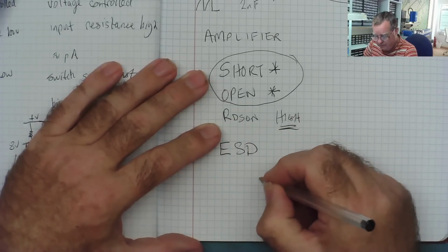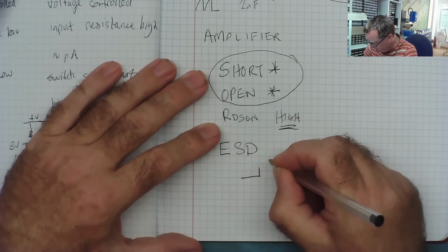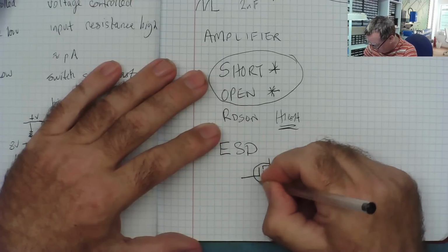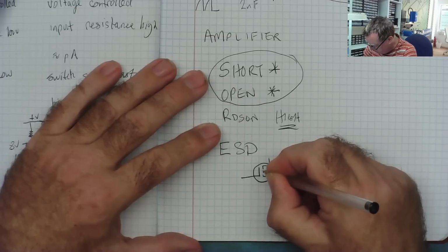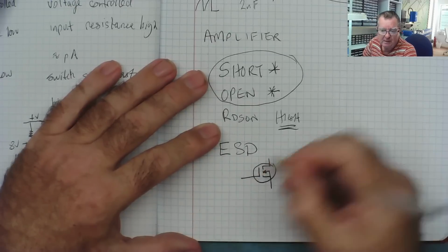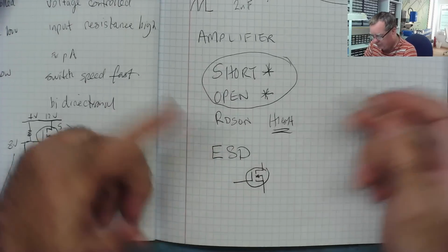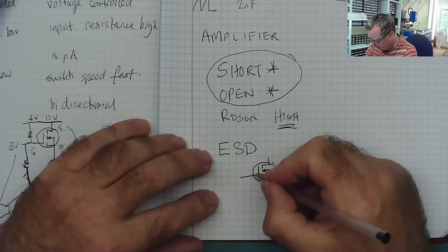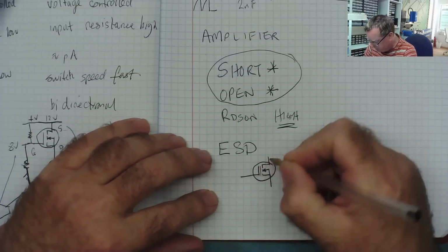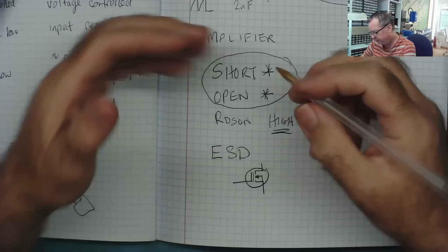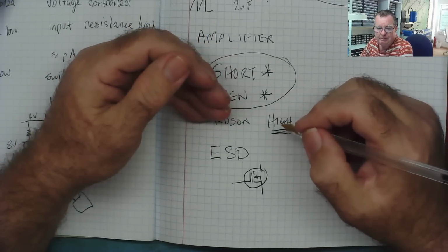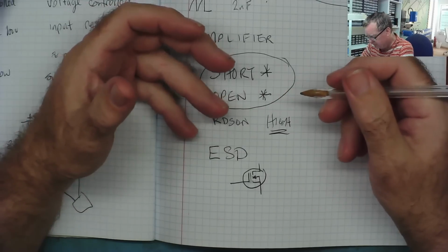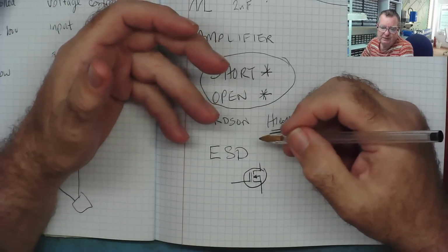You could see that the MOSFET would turn on using my multimeter when I applied some voltage to the gate. So I touch the gate with my multimeter. I'm showing you it gives about 3.8 volts. It turns on. And when I take the multimeter away, it stays turned on because the effective internal capacitor stays charged up. This can be a problem, especially in VRMs, but also amplifier circuits and many places you find MOSFETs.